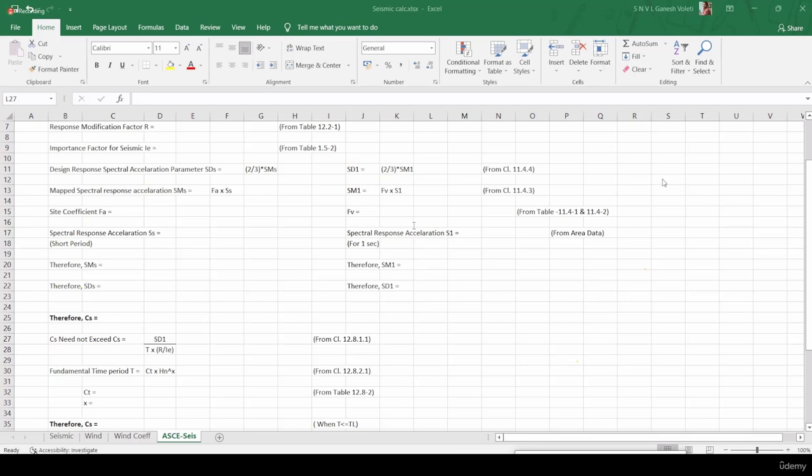Rajendra Kumar, you have asked some question regarding external pressure coefficients in 90-degree wind. I think in 90-degree wind, you can take both the cases, no problem at all. But load cases have to be increased. Suppose we have taken 6 cases only, you have to take 8 wind load cases. If the customer allows you more time, you can do that, no problem at all. Half cladding case, what is half cladding? Maybe he is talking about openings. Just go through the openings clause.